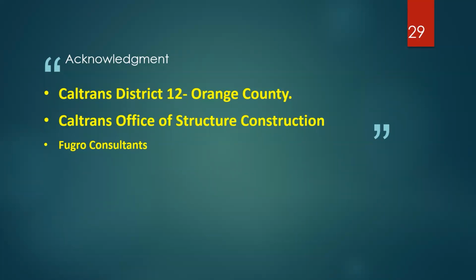So the CPT is excellent for that, obviously. So that was another element. The interlayering was there, and also at greater depth we had very dense sand. That's where we terminated the tip of the pile, which was at a depth of about, in some areas, 80 or 100 feet, or maybe deeper. But that's about it. The length of the piles was pretty much in the area of 80 feet or so, approximately.